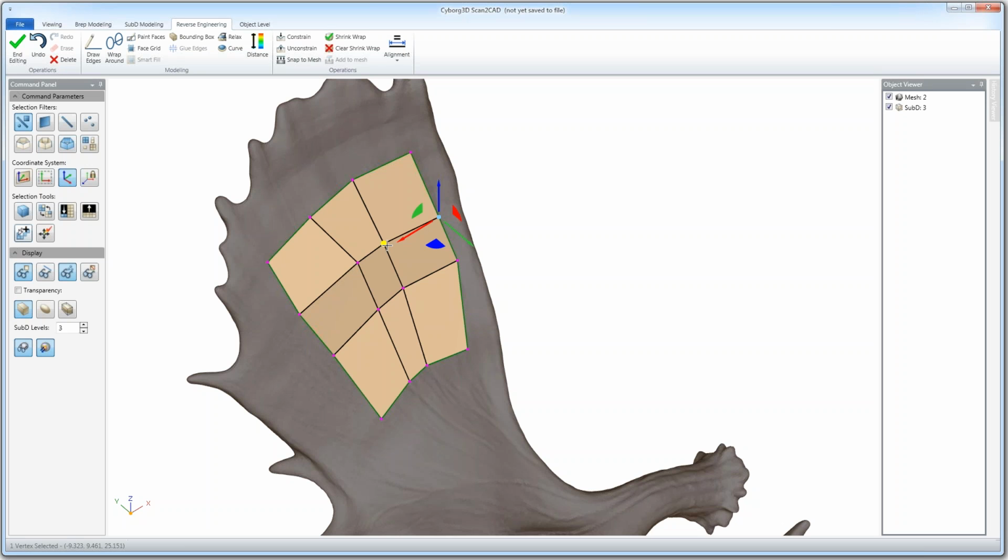That's what happens occasionally when you get a thin model like this: you can't really tell whether you're on the front side or the back side. One of the things you can do is go up here, in the document settings, and adjust the reference mesh Z-scale as well. It will tell you that's on the back, and you can see it better there.